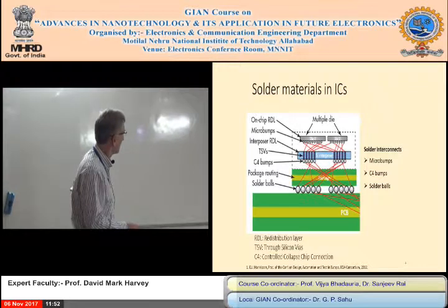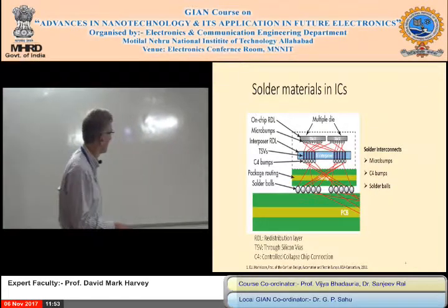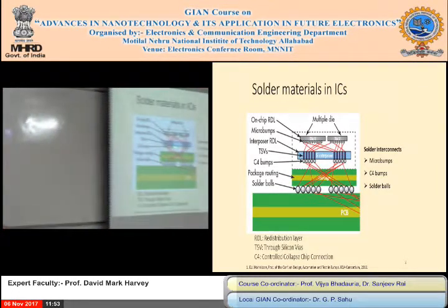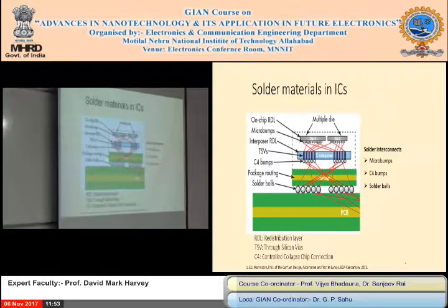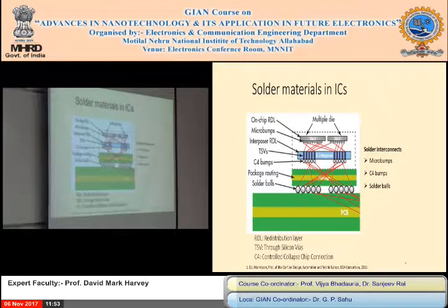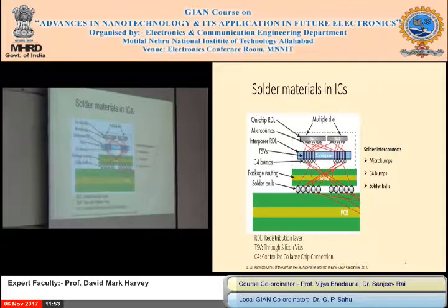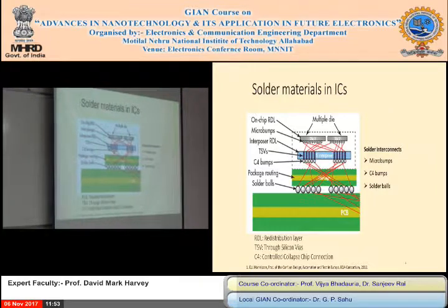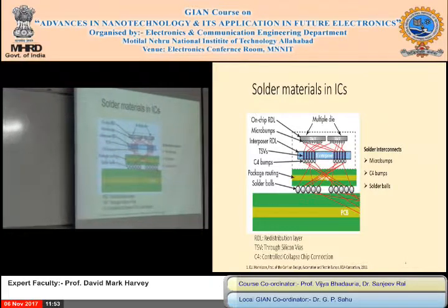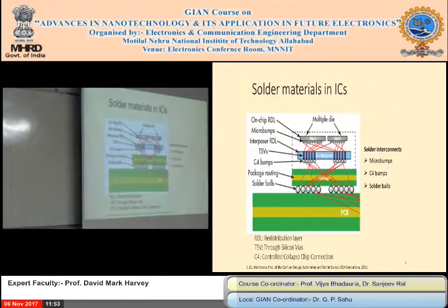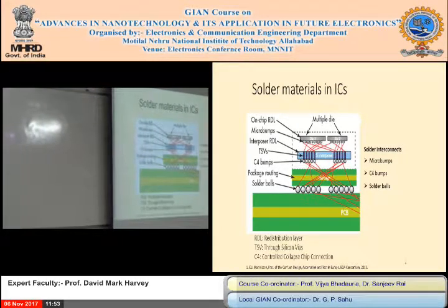And then finally, this is sometimes called an interposer board, with wires on, and sometimes we call this an interposer. The names don't really matter. There's different names coming in the market. The trick is there's a lot of layers there, a lot of connections that need to be made, and it's getting smaller. The solder joints are getting smaller. As things get smaller, they're not as strong per joint because it's smaller. So that's another possible problem.